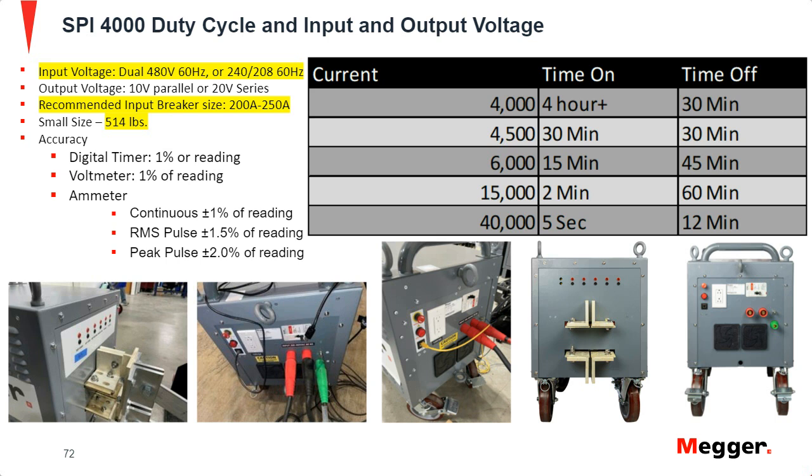So contact timing is typically a test you do on medium voltage and high voltage circuit breakers. You don't perform that on low voltage circuit breakers. On low voltage circuit breakers, we're performing primary injection to test the trip times. We want to see how quickly it could trip if there's an instantaneous fault, like a short circuit fault. And we also want to see how the breaker would trip if there's a long time fault.